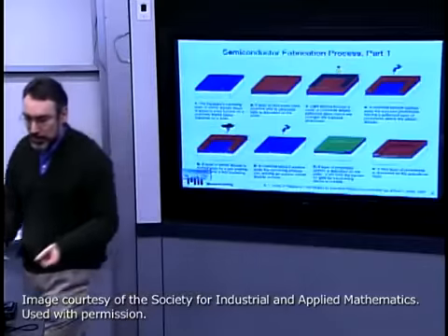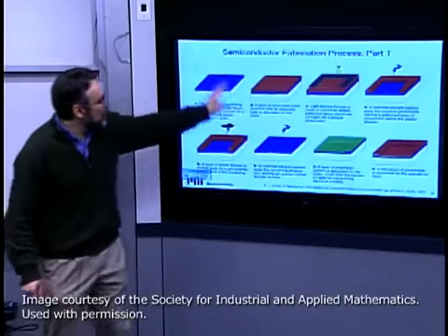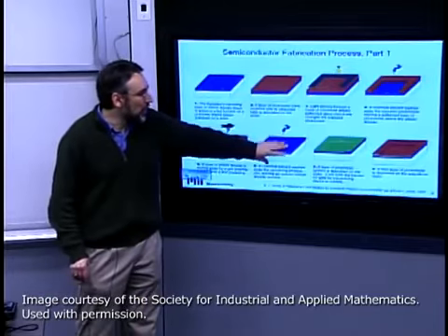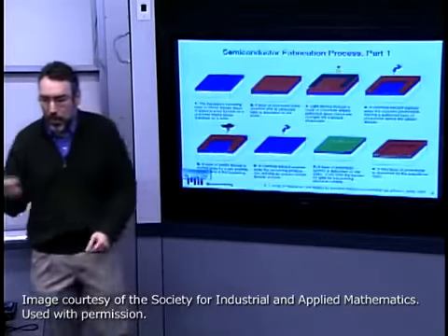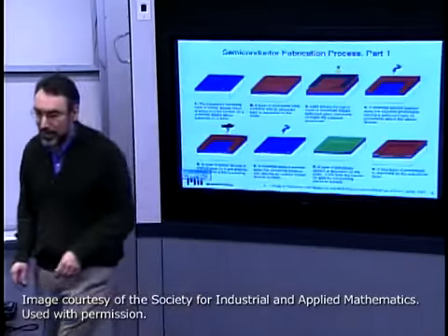We've done that sequence. We've now deposited or grown and then spatially differentiated to create one level of the structure. And now we're going to repeat that kind of idea multiple times and then mix in a few additional transformation steps. The next step here is we're depositing our polysilicon layer.